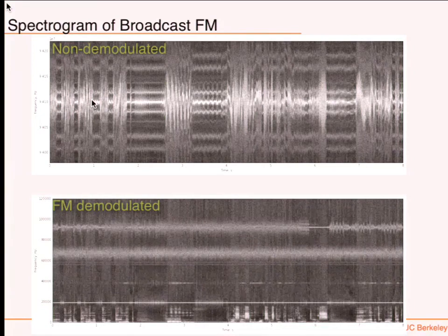So just look at the raw RF and look at what the spectrogram is, and you'll see that it looks like it's frequency modulated, because you see this is speech, I think. And when you have speech, it's kind of obvious when it starts and stops. And it's frequency modulated because you see that the information is encoded in the frequency. So the frequency changes over time. You're going to look at a spectrogram over about 8 seconds.